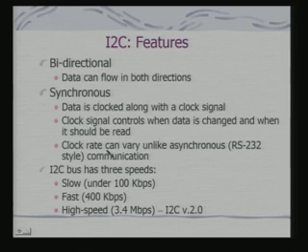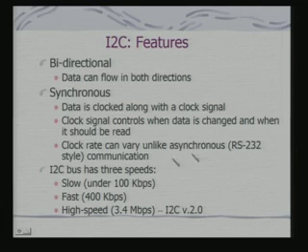The clock rate can vary, unlike asynchronous communication. Okay? In an asynchronous communication like RS-232C, you have to have a fixed clock rate because you are sampling the bits. That means you are finding out whether there is a start of transmission or not at the clock intervals. But since here the clock is being transmitted along with the data, the clock determines the valid data transition.